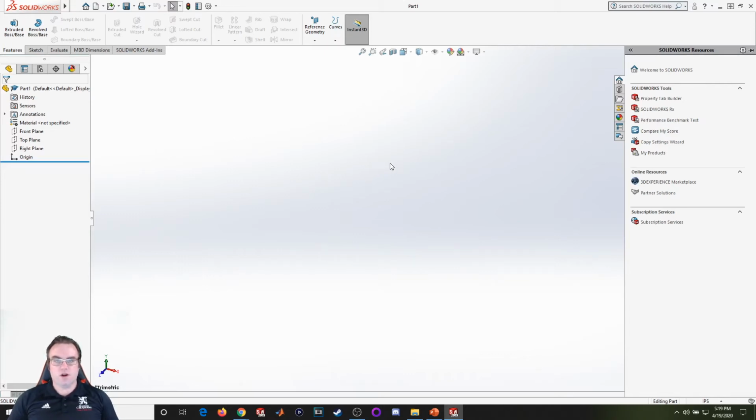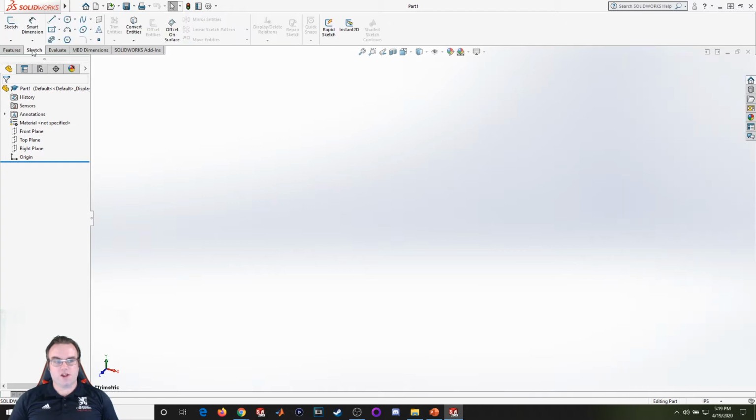So for this video we're going to start going over what it means to sketch in 3D. If we come up here to the Sketch tab, there's a little drop down here. We can click on 3D Sketch, and that's going to allow us to create sketch elements that exist in 3 dimensions.